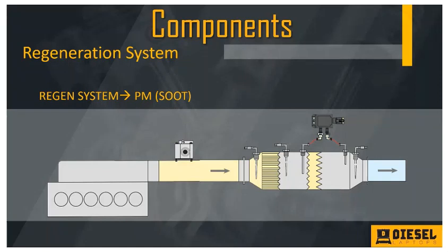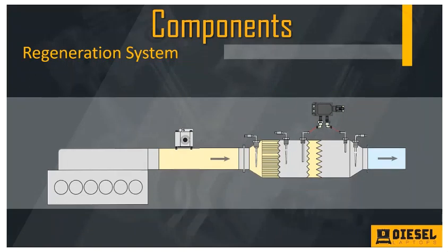they have a job to capture ash, to capture soot, to oxidize that soot through high temperatures, turn that soot into a gas so that chamber can breathe again. Once that chamber is slapped full of ash, we will have to service that assembly. So this was primarily introduced in 2007 here in America.